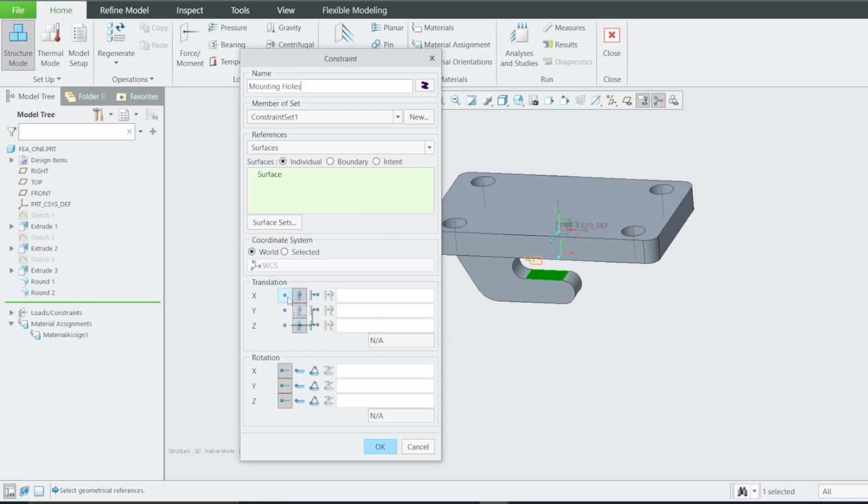This first means free, second means fixed. That means you can define, we can say this hole can move maybe 1 mm. You can prescribe the initial movement, especially for bridge analysis, whereby when the bridge is at high temperatures, the bridge can expand by a certain amount. This way it is free to move up to maybe 5 mm at the translation. But rotation, because it's 3D, once you define translation, you don't need to define rotation.